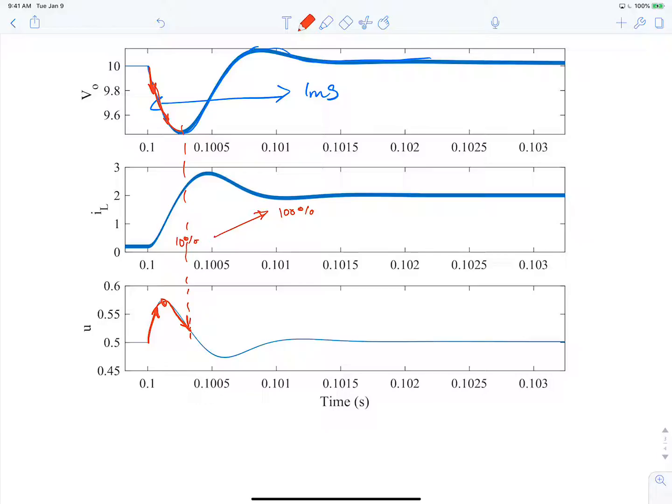And you really have to have a good understanding of what it's doing and how to effectively make your controller not overact to that, or essentially be stable in the sense of having a right hand plane zero.